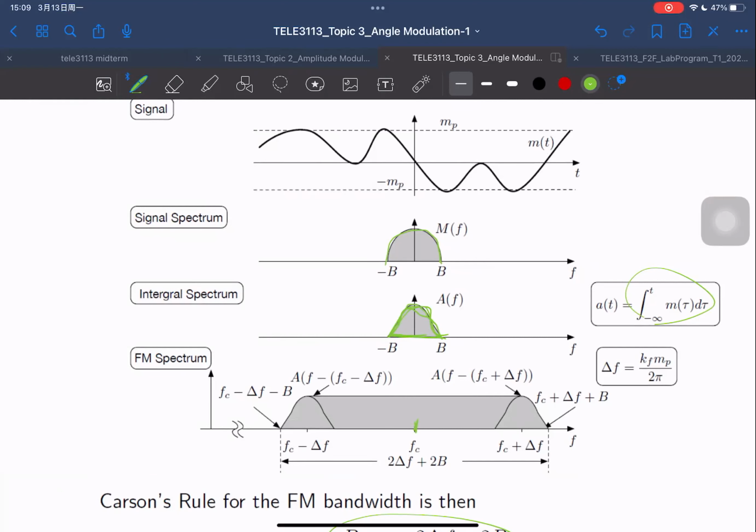Yeah, so the idea of this one is, if you use cos 2 pi 40t and multiply it with our carrier frequency, let's say cos omega ct, we're going to use the trigonometric identity. You're going to do a half first. You're going to have a half cos 2 pi 40t plus omega ct, and plus cos 2 pi 40t minus omega ct, right? So this is the first half you get.